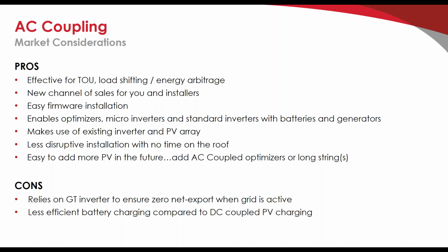And then the second con is that AC coupling is, of course, less efficient for battery charging compared to if you went direct from PV, DC to DC, from that PV array into the battery.